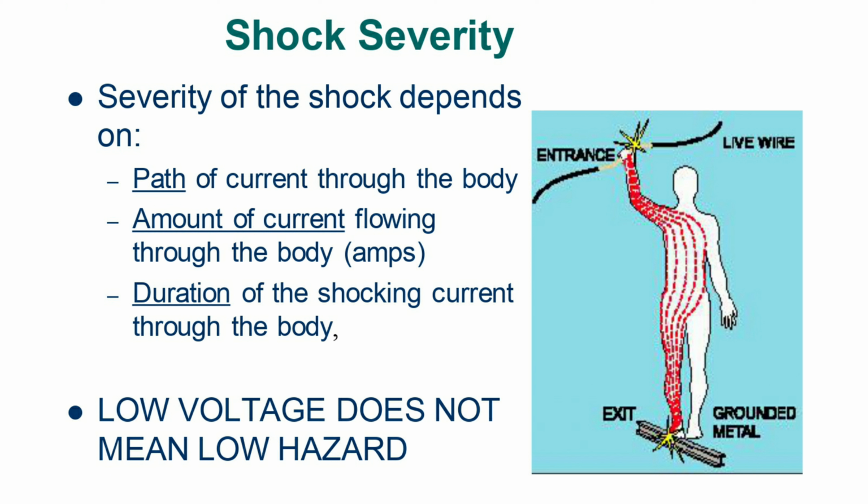Shock severity. The severity of the shock depends on the path of current through the body, the amount of current flowing through the body, in amps, and the duration of the shocking current through the body. Low voltage does not mean low hazard.